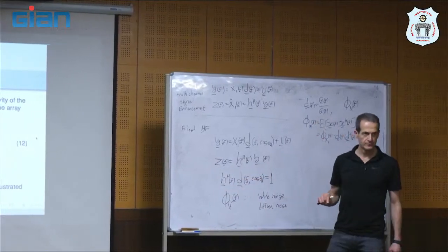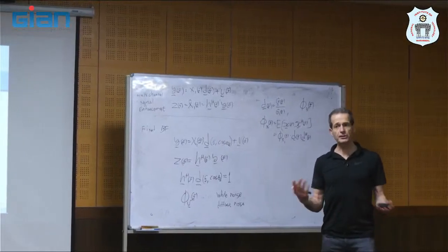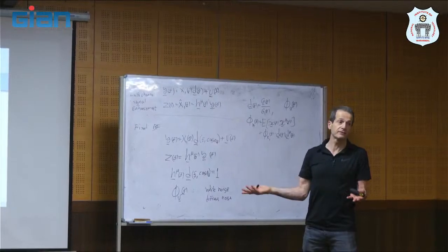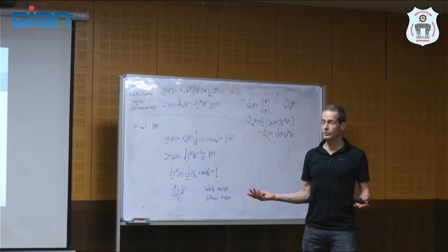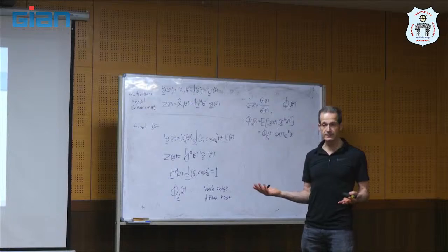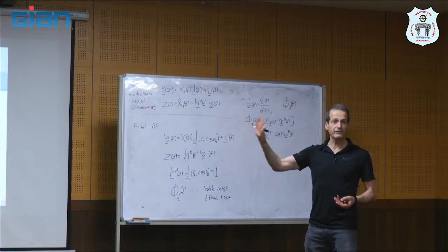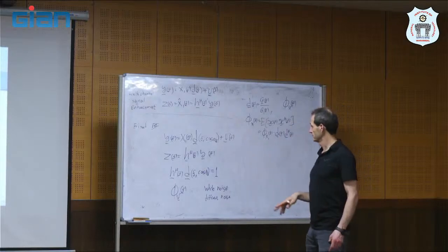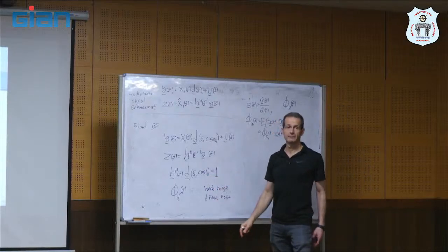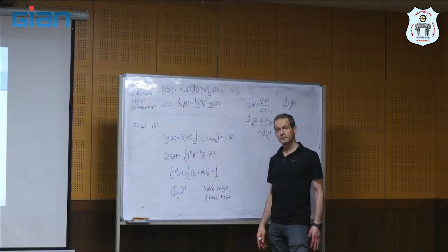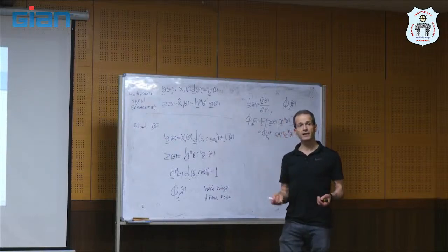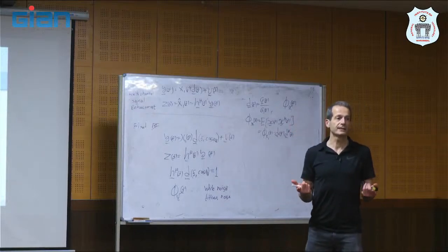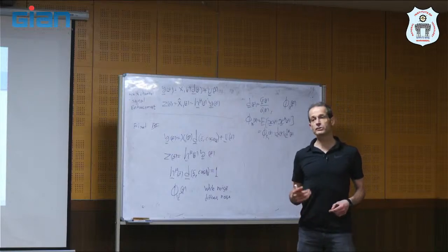Undistorted. So generally, we can measure what is the sensitivity. We call it sensitivity. What is the sensitivity of the array to a propagating wave that comes from a certain direction, theta, other than theta d? Sensitivity means what is the amplitude, the phase, and so on. What is the signal that will be measured from that direction?